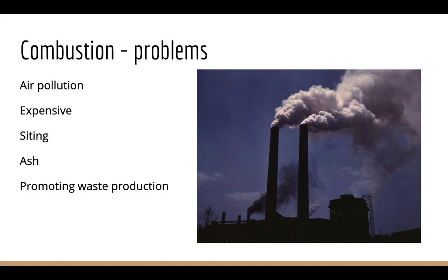For your ash, if you have any metals or hazardous substances, you would need to find a secure landfill for that ash. One of the biggest problems with incineration is it actually promotes waste production. These incineration factories need burnable materials in order to operate and in order to produce that waste to energy process. They will compete with recycling for burnable materials, and they need to have this continuous supply of municipal solid waste in order to operate and produce that energy.